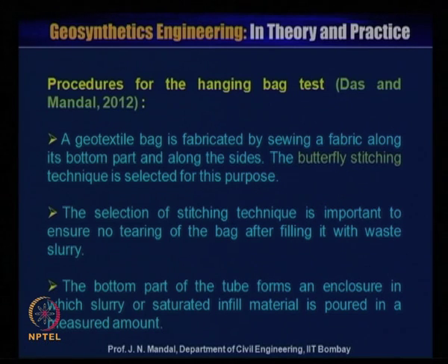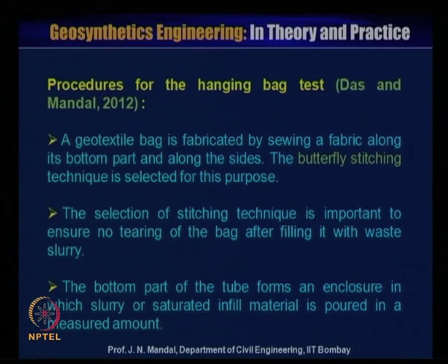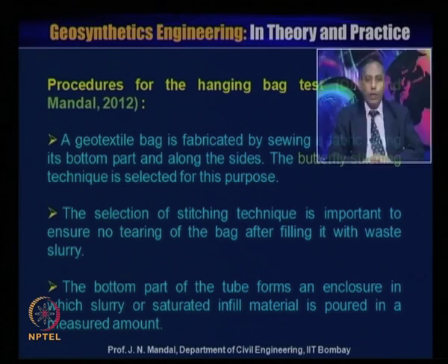Now, a geotextile bag is fabricated by sewing a fabric along its bottom part and along the side. The butterfly stitching technique is selected for this purpose. The selection of stitching technique is important to ensure no tearing of the bag after filling it with waste slurry. The bottom part of the tube forms an enclosure in which the slurry or the saturated infill material is poured